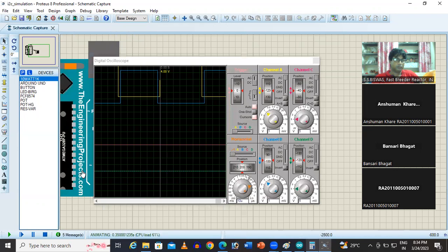Now you see, here it is very clear. Once the yellow pulse toggled from high to low, and when the blue pulse is toggling from low to high, in between there is some gap. So there is no question that both switches can short. Both the switches can be on at the same time.